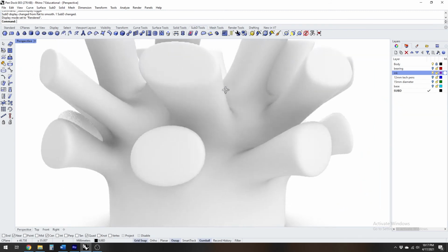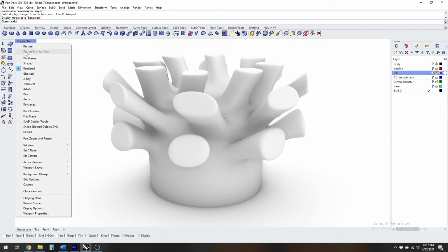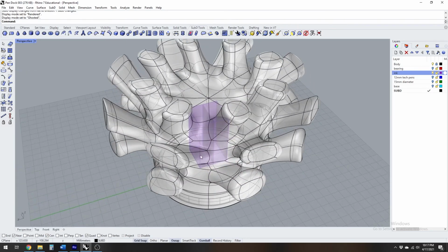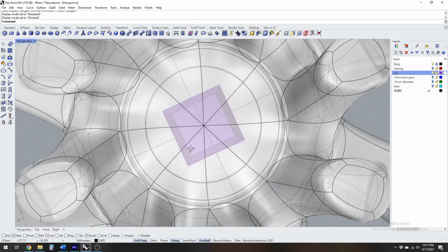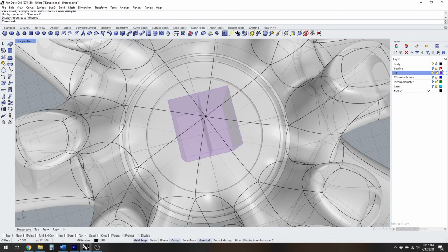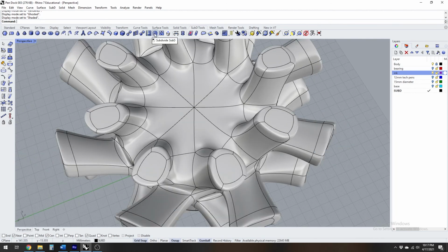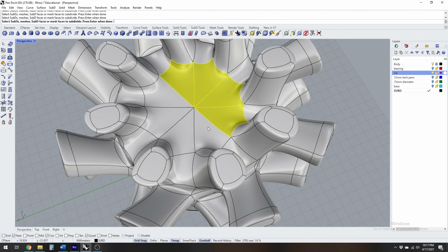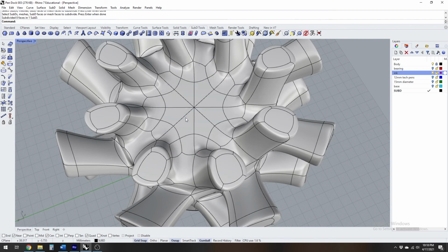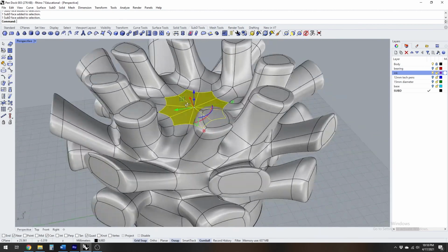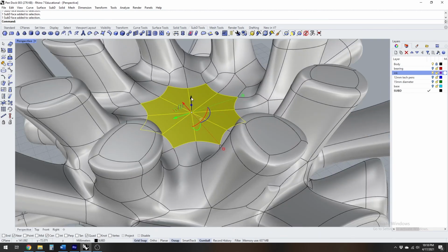So I will say that so far my understanding of the workflow is that you spend a significant amount of time in your SubD tools making really fluid dynamic changes. And then you check those surfaces with your NURBS surfaces to make sure that the clearances and relationships are as expected. So for instance, here I need to make clearance for the ink bottles. So I'm subdividing the center of the cylinder, selecting a square-ish shape, and then I'm going to extrude downwards in order to create this pocket that the ink will fill into.